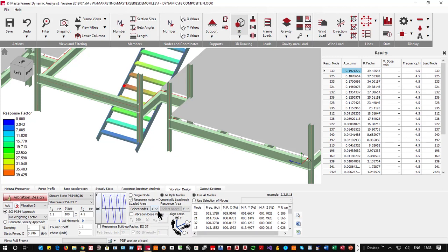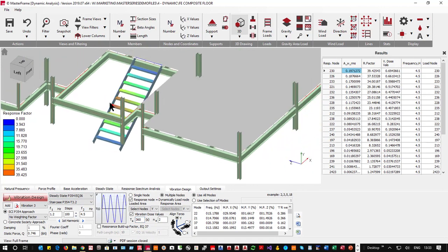distance. So what we're going to do is we're going to say, let's go for a vibration dose value. And we're going to say, let's go for 360 seconds. That is 6 minutes of excitation. And we're going to say that only one person comes down through here in any 6 minutes. So in this case, we'll just drop that to 1, or 1 pair of people. And we're now going to see what our values are. But if I just reanalyze for that, they've come down to 0.6.